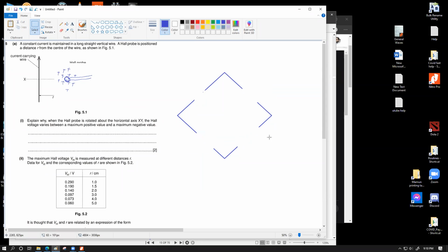Thank you. So let's say you have a kite structure like this, irrespective of the connection points. Obviously, supply has to come from two opposite sides, and the drain has to come from two opposite sides. You can always make a good bridge rectifier as long as you make the parallel sides having the same direction. So you make the parallel sides aiming the same direction, and then the other two sides aiming the same opposite direction. This will always work.